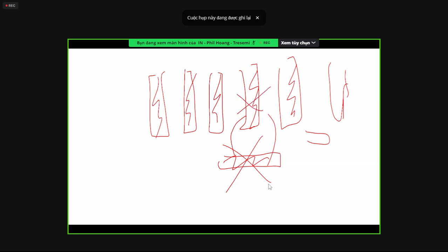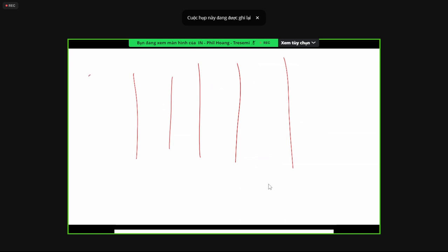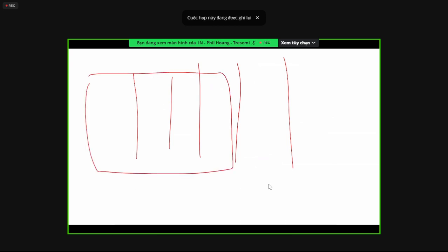So you have to be either just one direction, vertical or horizontal. If you have a macro here, and all your poly is like that, and you have standard cells here where the poly is vertical, then you're good.